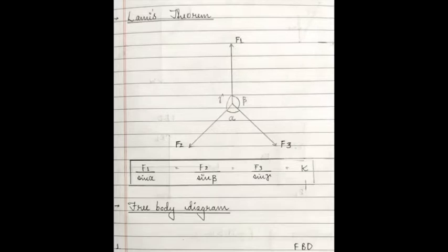Not only moving, the rotational effect is also a matter, where you can stop the body from moving. That is called moment. You understand the concept of moment? Moment is nothing but the rotational effect on a body, or the product of the magnitude of the force and the perpendicular distance. You should make the moment, the resultant, both things equal to 0. Then only I can say the body is in equilibrium or at rest. You are going to solve lots of problems based on this particular concept. You have already solved it.